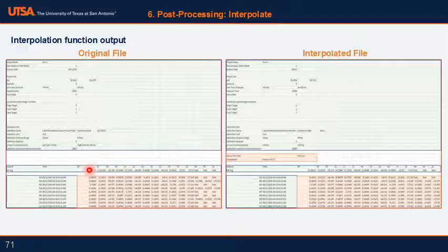What it'll show you is the XYZ coordinates of the targets from those reference images. So this line gives your zero deformation state. You'll notice that targets are numbered from 0 on, so x0, y0, z0 are the coordinates of the first target you selected, x1, y1, z1 are the coordinates of the second one, and so on, every column. The columns after that are all the other targets. Every file starts off like this, and you also have the date and the time, and the frame number over here.